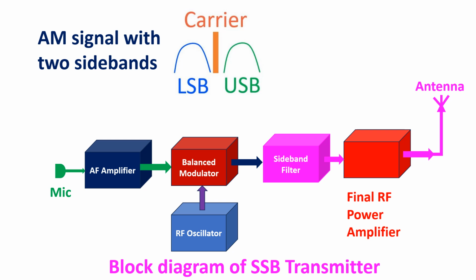In modern radio transmitters used by amateur radio operators, single sideband or SSB is used to maximize the range with lower output power. In single sideband transmitter, the audio wave modulates the RF carrier wave in a section known as balanced modulator, which has the output as double sideband without a carrier wave.